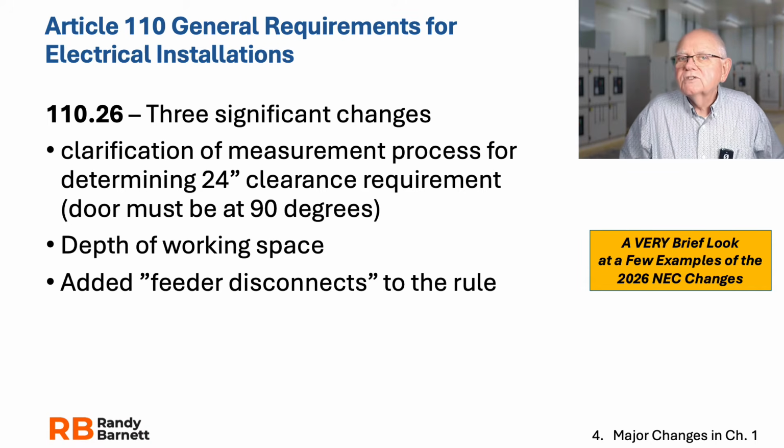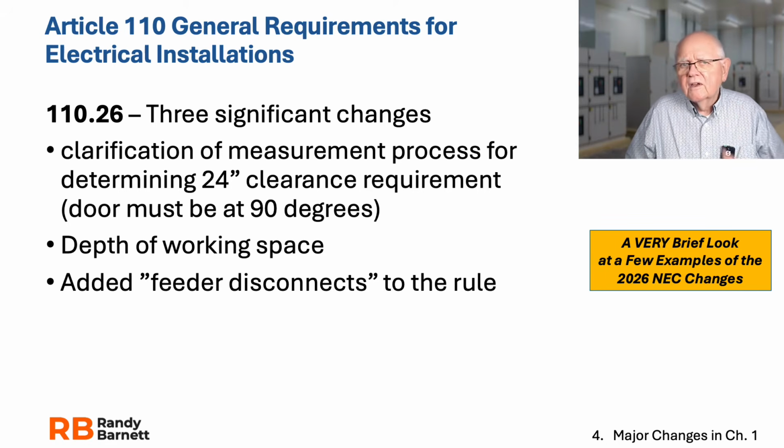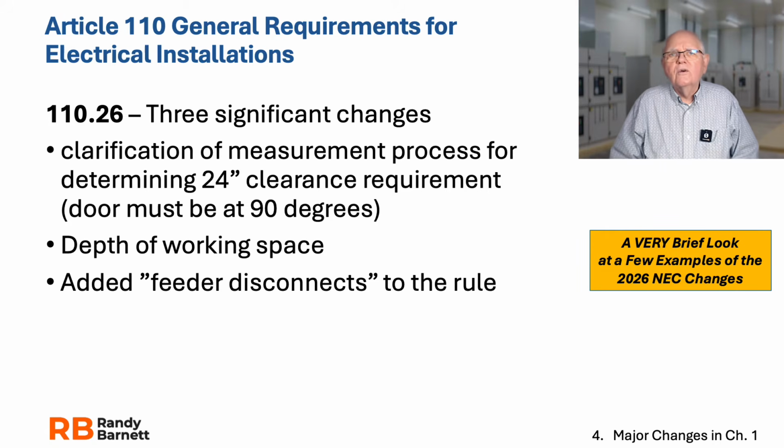Take a look at your changes on depth of working space, and they've added feeder disconnects to the rule as well for spaces about feeder disconnects. So 110.26, especially important one in the installation world, make sure you meet those new requirements.